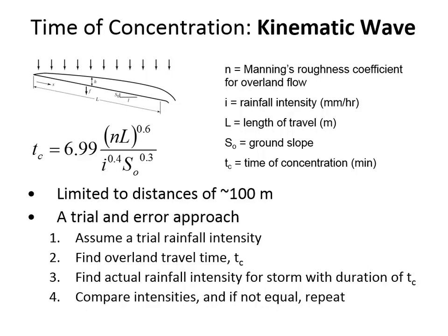And the same is true with the rainfall intensity. This is saying that the more intense the rain, what they're taking into account here is that a more intense rainstorm is going to have a greater water depth, and then more of your flow depth is further away from the resistance of whatever the surface is that's resisting. So if it's a concrete surface, if you have a deeper flow depth, then more of the cross-section of the flow is further from that resistant surface, and so that'll decrease the travel time.